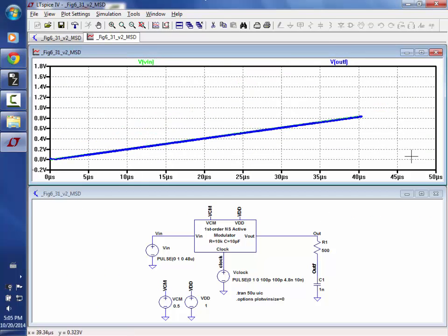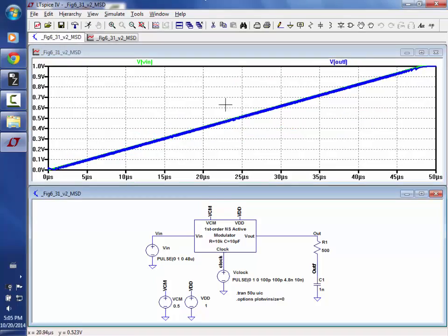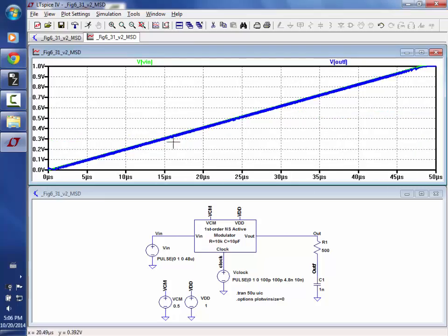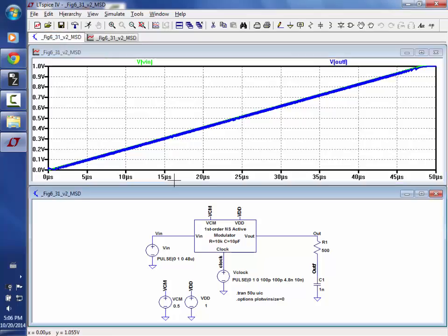of a dead zone. So we'll hit run, and as everybody can see, we go right around this part where we had problems, which was 0.5 volt. And you can see I get a little bit, but it wasn't like the passive modulator. Does everybody see that? Just looking at this, it's much more linear than what I had with the passive modulator. Any questions? So if I were to ask you why, I'm getting rid of the distortion term.